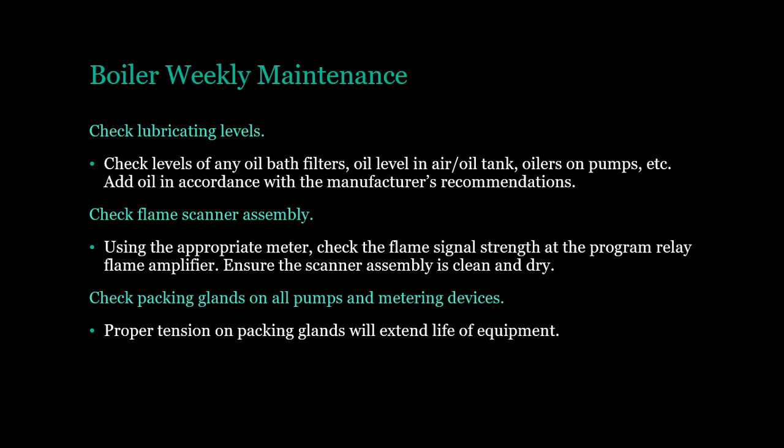Check flame scanner assembly. Using the appropriate meter, check the flame signal strength at the program relay flame amplifier. Ensure the scanner assembly is clean and dry. Check packing glands on all pumps and metering devices. Proper tension on packing glands will extend life of equipment.